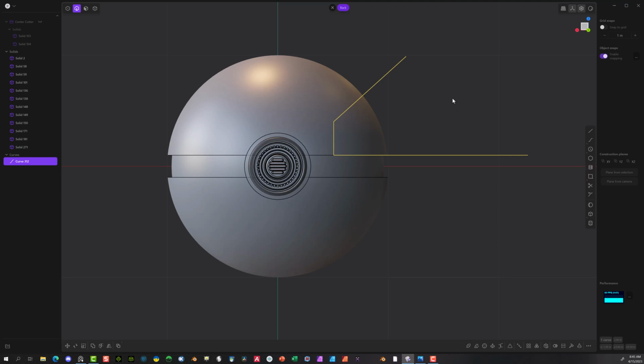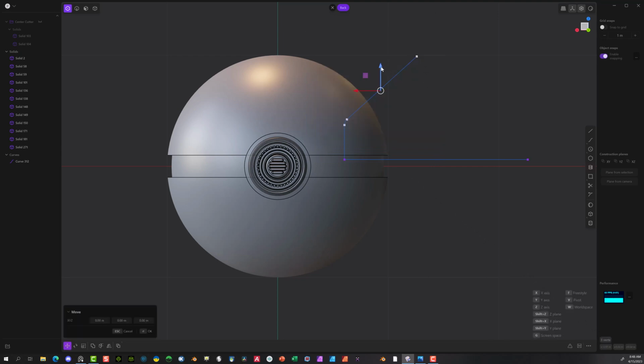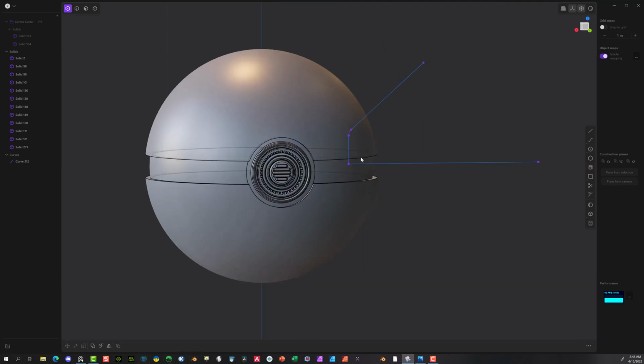One thing I'd like to do is go ahead and make this rounded. So we're going to select this here. We'll just go a little bit like that. I think I'll bring this down just a little bit more. G key. Like that. There we go. See how this looks. I'm going to go ahead and do this too. Just hit the fillet key again. I don't want it past that, so there we go. All right, so that's that.